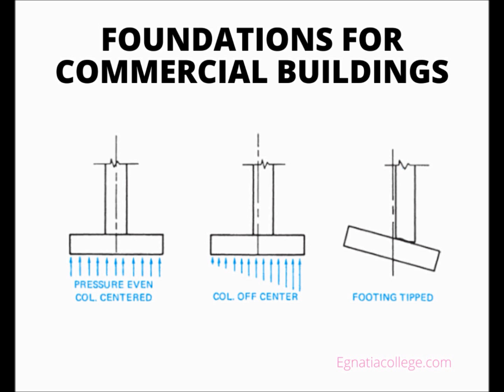The drawings consist of a plan that shows the layout of the foundation and the major dimensions, and detailed drawings that describe reinforcement, expansion joints, and variations in design at special locations. The placement of column footings is indicated by referencing the structural grid coordinates. The structural grid indicates where the center line of the column will be, but it is very important that the footing be placed accurately on the center. If the column does not rest on the center of the footing, it may tip due to the uneven pressure on the soil below.